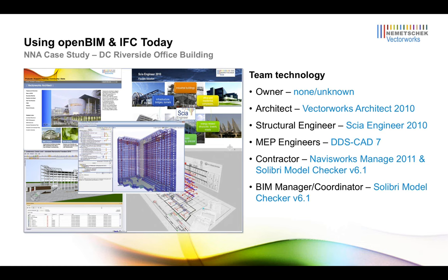And the contractor might be using Navisworks Manage as a visualization tool and as a process timeline tool, and then also the Solibri Model Checker to do things like the information takeoffs. But then additionally, you have the BIM manager or coordinator using Solibri Model Checker as a way of analyzing, reporting on, and coordinating all of this BIM data, right?